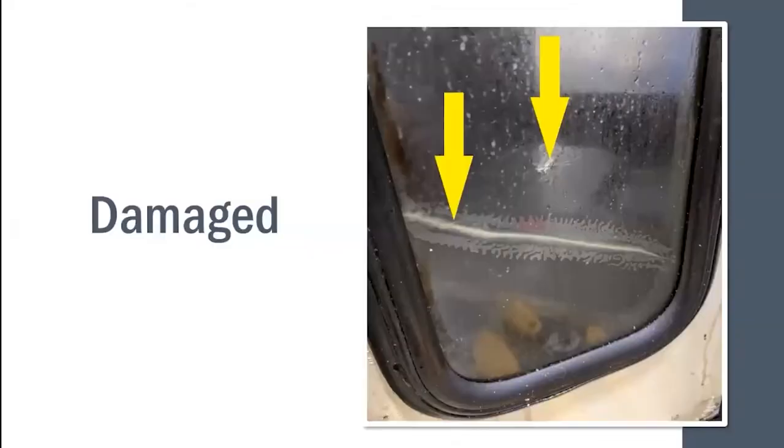Another variation on damage to the guard. This is a polycarbonate window on a CNC enclosed machine that's taken a couple of hits from ejected parts or cutting tools inside. So the polycarbonate has been damaged. If we see that, we want to note it and have it replaced, because the integrity of that polycarbonate window to withstand another impact has been compromised.